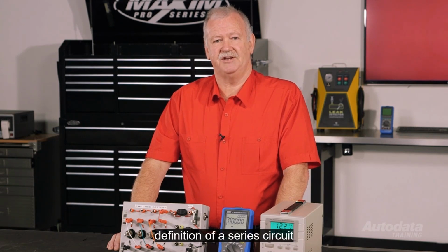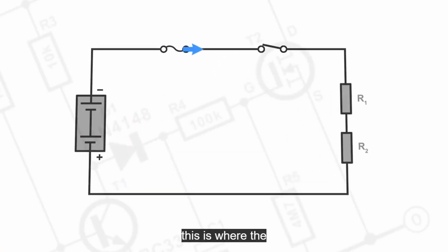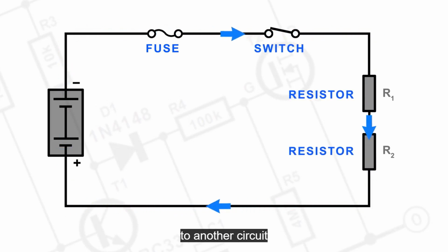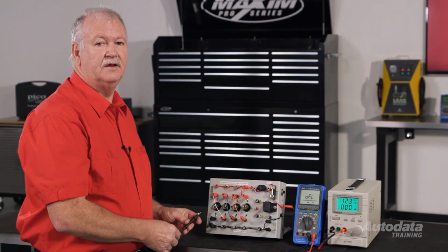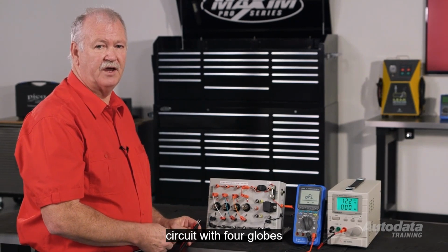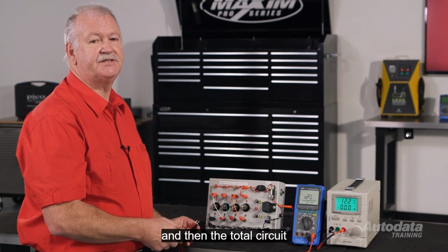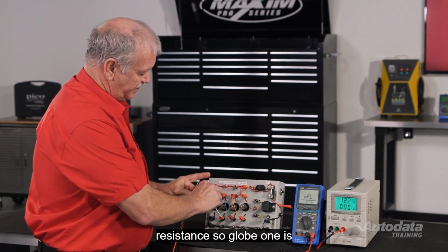Let's start with a definition of a series circuit. This is where the current passes through each element in turn without branching off to another circuit. I've got here a series circuit with 4 globes. I'm going to start by measuring each of the globes' resistance and then the total circuit resistance.